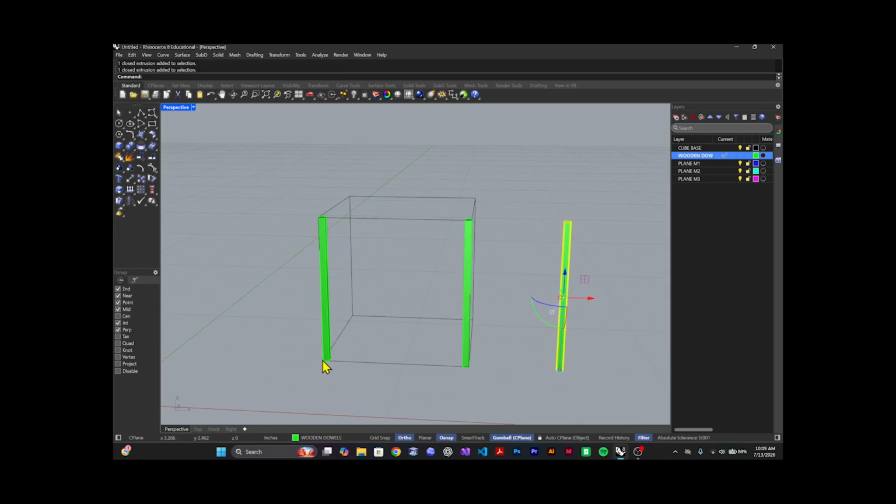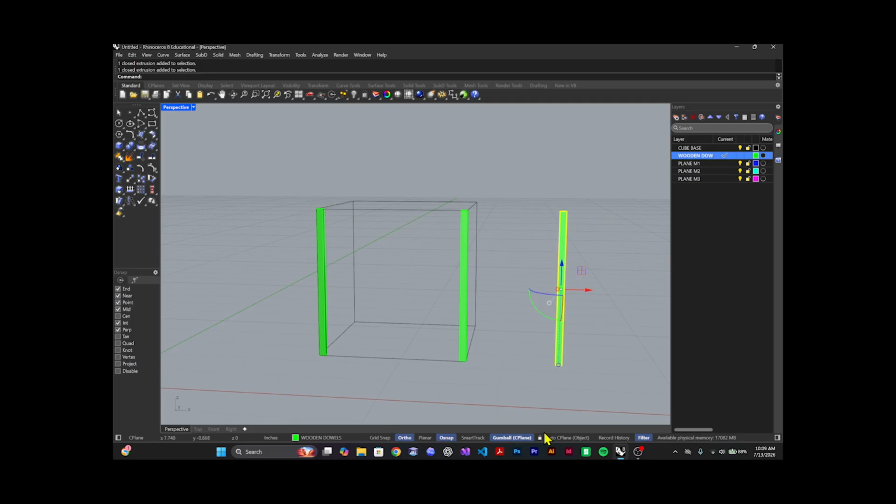So now what we need to do is rotate this guy horizontally, so it becomes the bottom part of my structure, right? This is where this little guy comes in very handy, the combo. We can just rotate it, and if you have the ortho command on, it's going to rotate it horizontally, perfectly aligned.